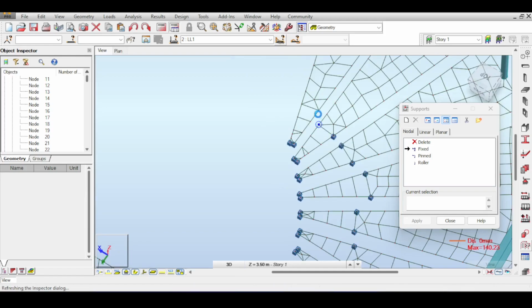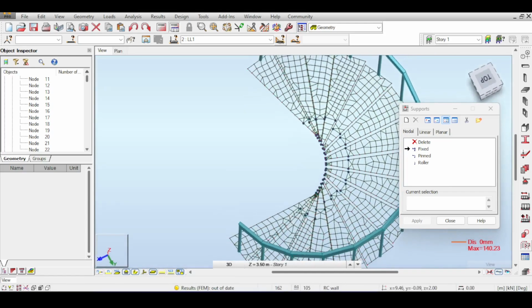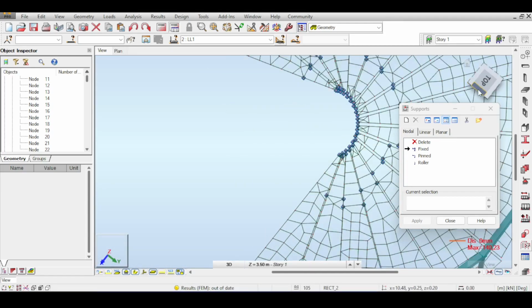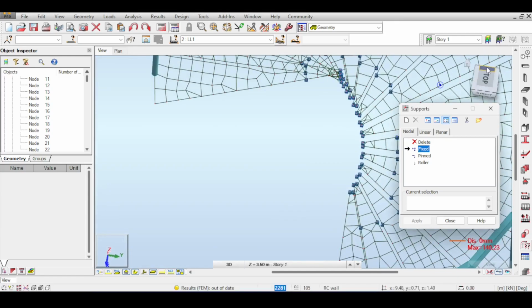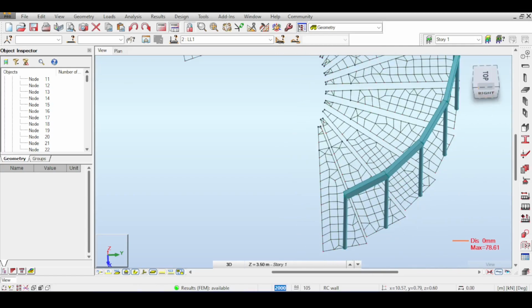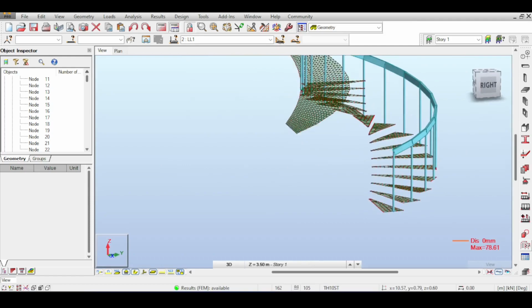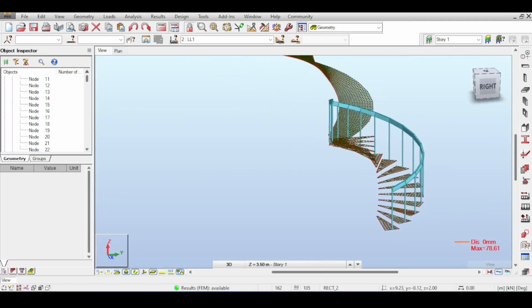You can make it correctly if you basically make R equals, for example, 0.75, and then fix everything on that path. We have done this before. But for now, I just want to prove a point here, not to model perfectly. So let's take a look. Much better deflection. 70 millimeters, still a lot, but at least the 1000 millimeter deflection are away now. And feel free to tell me what you think in the comment section.